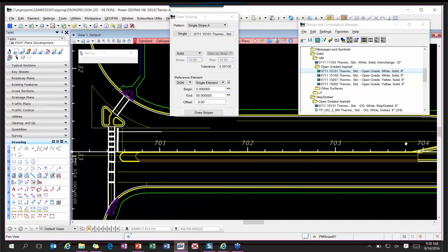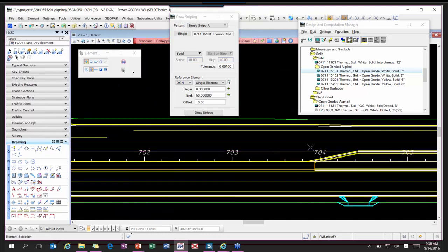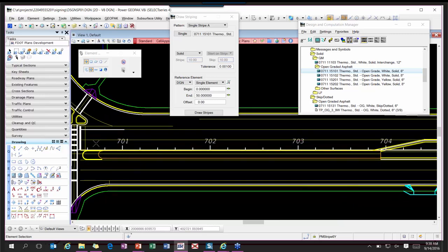All right. Part of my construction lines, there's a couple of ways that I could have done this. I can grab all of these as a selection set and just draw one line in here. But instead, I broke it. I went into the design standards for design speed of 45 miles per hour. The L1 value, which is the distance from where the taper starts to where your solid line needs to start, is 85 feet. Okay, so this line here is 85 feet long.